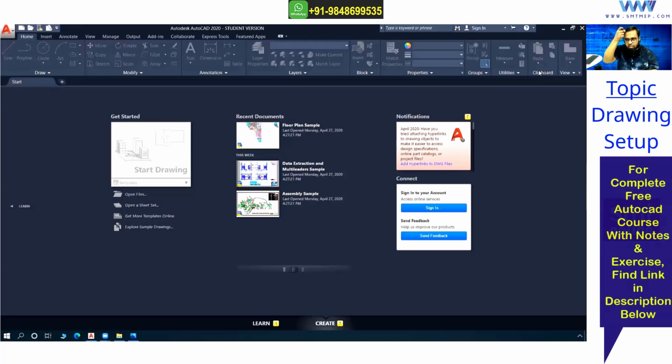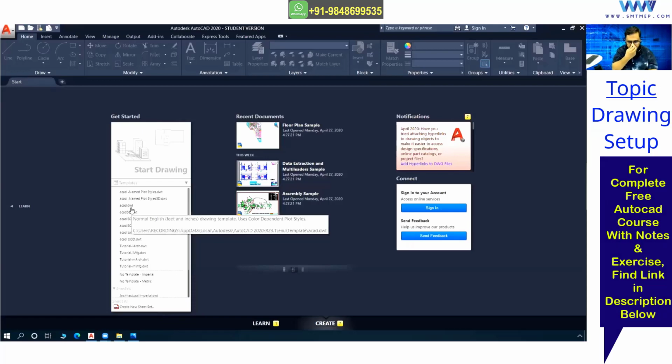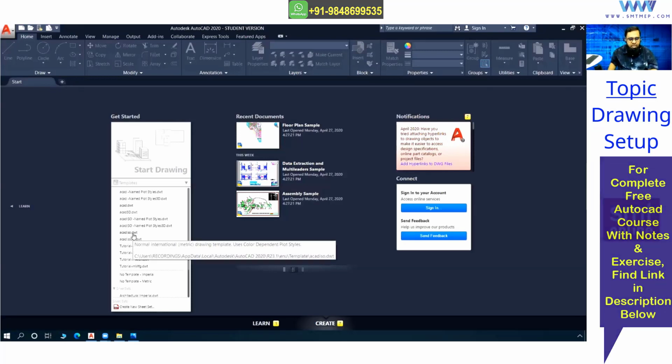So if you do not set the limit, what will happen? You'll get confusion. I'll show you. So here I'm going to create a new file. You see, I already set the template. For example, I'm using ACAD, which is for the English system, and ACAD ISO for the metric system. So for example, I'm using this ACAD ISO for the metric system.